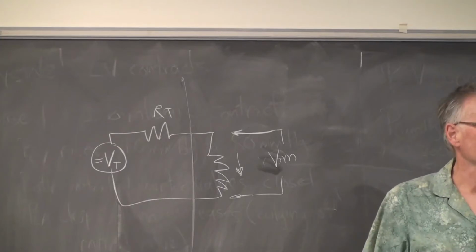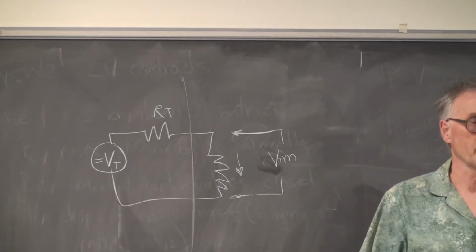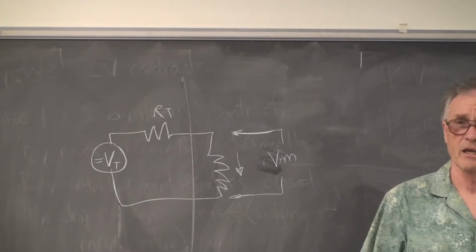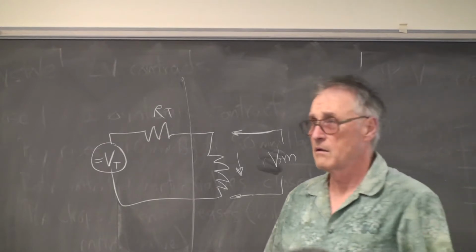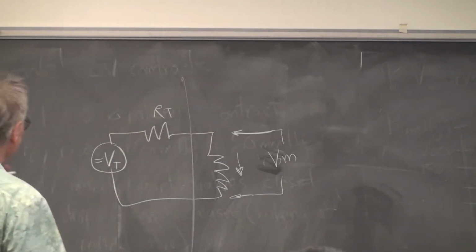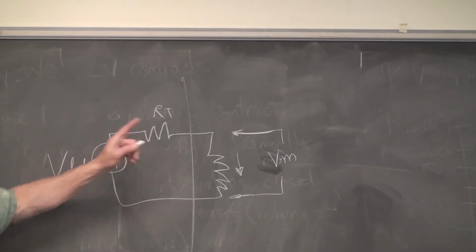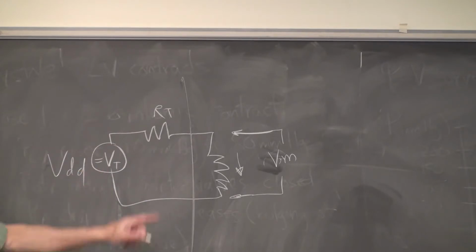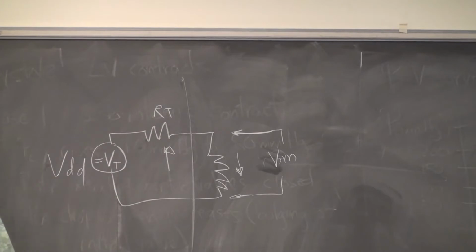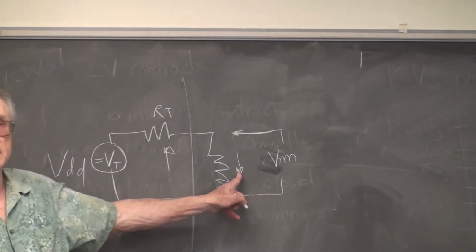Oh, come on, guys. It's a CMOS pair running between VDD and ground. What's VT? Is it VDD? It is VDD. Because if you don't put any load on a transistor, the output value is going to float up to the supply. Right? This is just a CMOS inverter output, so it's going to float up to the supply. So VT is VDD. What I'm asking for is this resistance, not this resistance.